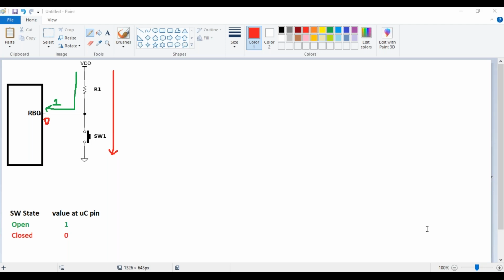It might attract noise, but it is not going to harm any devices. But due to the short circuit, there are chances where all of these devices might get damaged. Okay. So a short circuit is always more dangerous than that of a floating line.